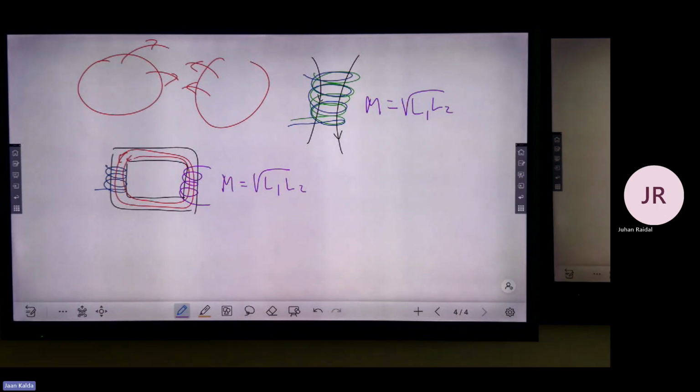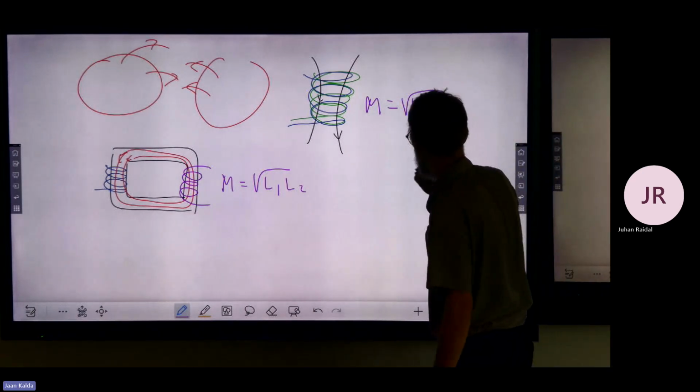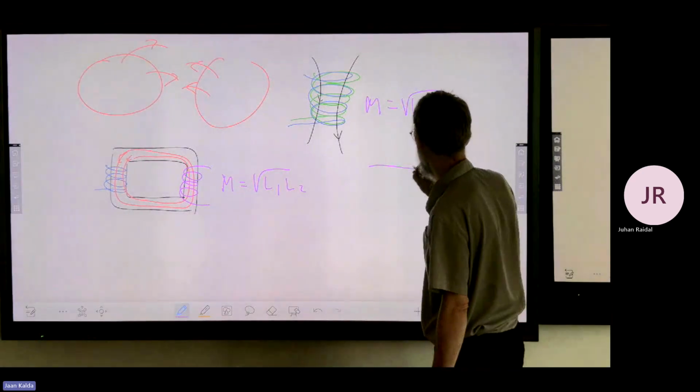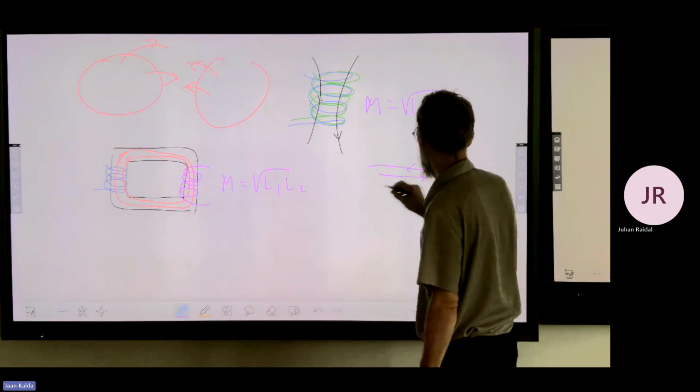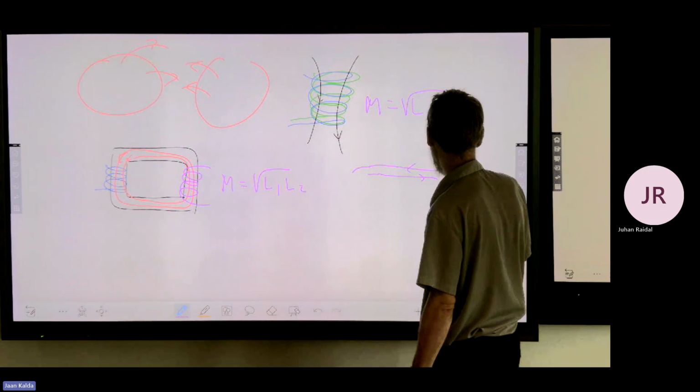So that device switches off your home electricity at the moment when the difference of currents in the incoming wire and outgoing wire is larger than 30 milliamperes. So suppose here your electricity comes in, and here it goes out, and here is your home device. So here is 230 volts.